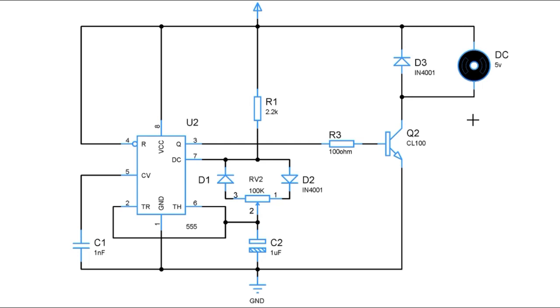So that's how a transistor is being used as a motor driver here, and it is not really possible to drive a DC motor using IC555. Even though the datasheet states it can handle up to 200 milliamps, it can get extremely hot, and it is very unlikely in practical application for IC555 to handle such current. So it is always suggested to use a transistor as a switch and connect it in this way. You can use either a PNP or NPN. This is an NPN transistor. You can use a PNP transistor as well to act as a motor driver here.